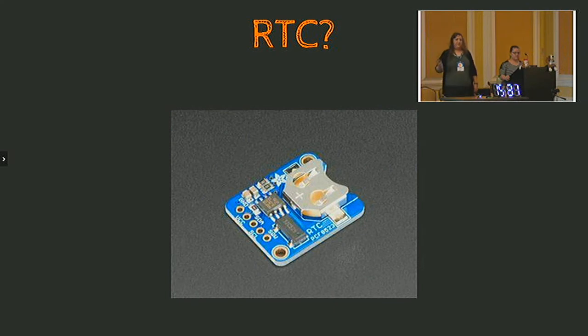She also mentioned an RTC module. So RTC stands for real-time clock. Everything that has a crystal is basically able to keep time, to count the time that goes by the number of ticks of the crystal. But an MCU, the processor in your computer, all that is not really precise. And so when you want to keep precise time, you usually use an RTC module. The RTC module also is able to keep time as a datetime object, a struct time in Python.